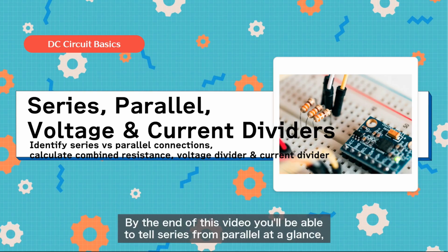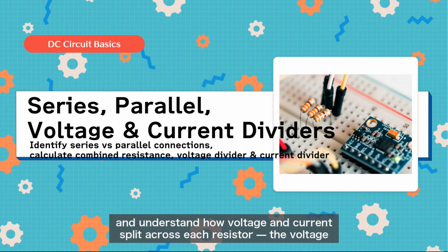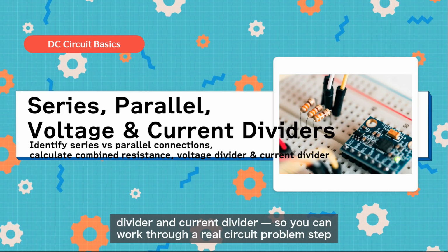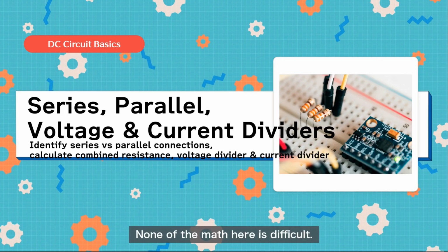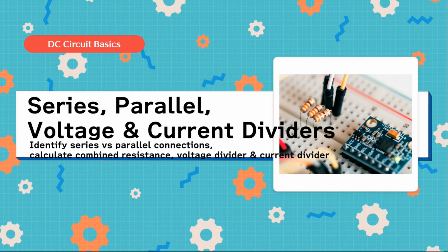By the end of this video, you'll be able to tell series from parallel at a glance, calculate the combined equivalent resistance, and understand how voltage and current split across each resistor, the voltage divider and current divider, so you can work through a real circuit problem step by step. None of the math here is difficult. Take it one step at a time and it will all click. Let's get started.